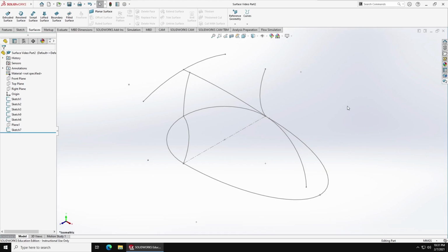First off, a little bit of information on how SolidWorks operates under the hood. SolidWorks doesn't actually produce solid objects. It only keeps track of their surfaces. It ensures that each object you create is watertight, meaning that the surfaces that make up the object don't have any gaps. Essentially, if the object were to be filled with water, none of it would spill out. All of the features that we've been using are actually a combination of several surface modeling tools, each one stitched together and polished to increase user friendliness.